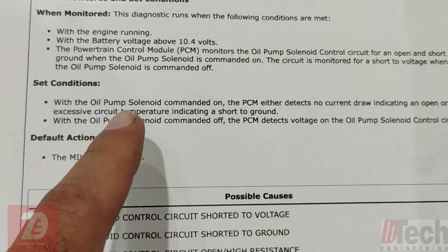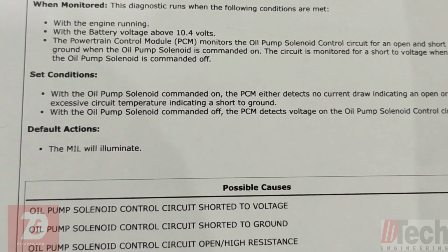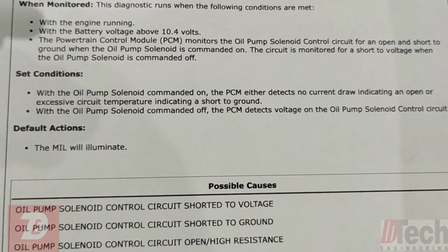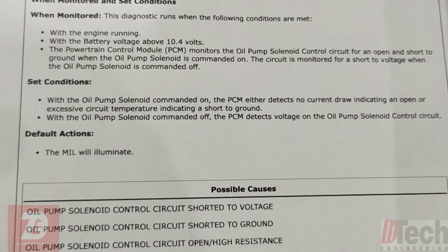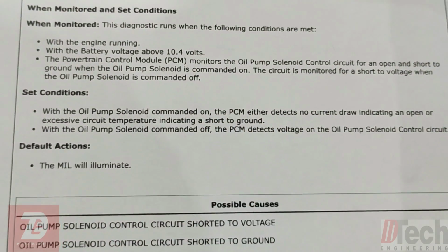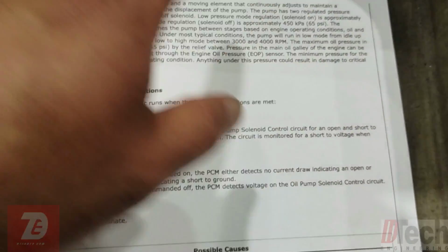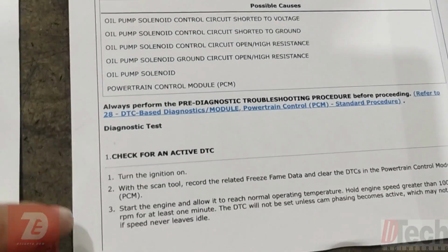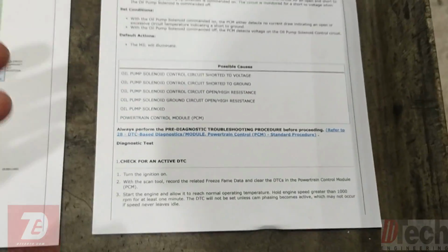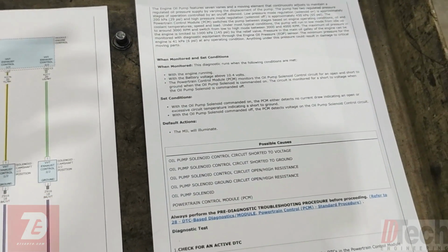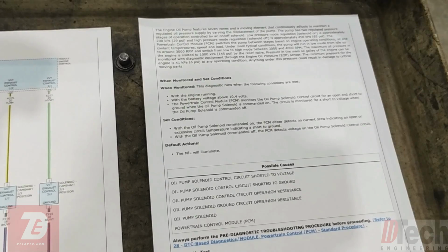With the oil pump solenoid commanded on, the PCM either detects no current draw indicating an open, or excessive circuit temperature indicating a short to ground. And so all this relevant information is pulled up for basically troubleshooting based off of that specific single trouble code